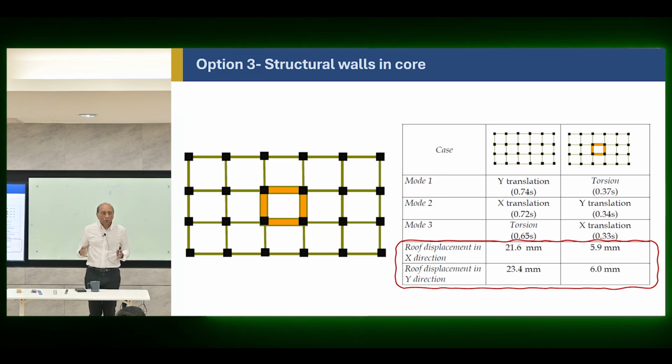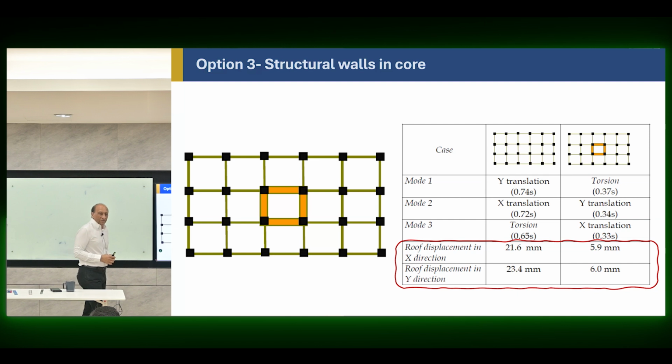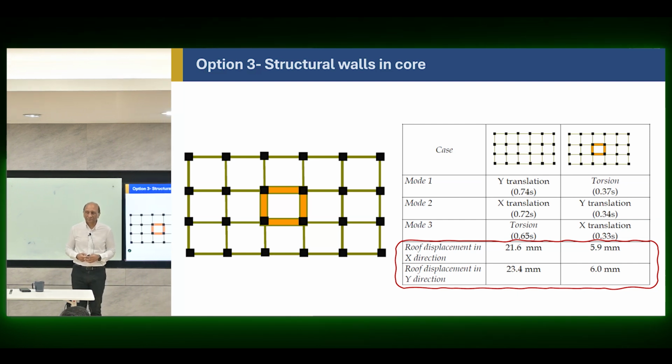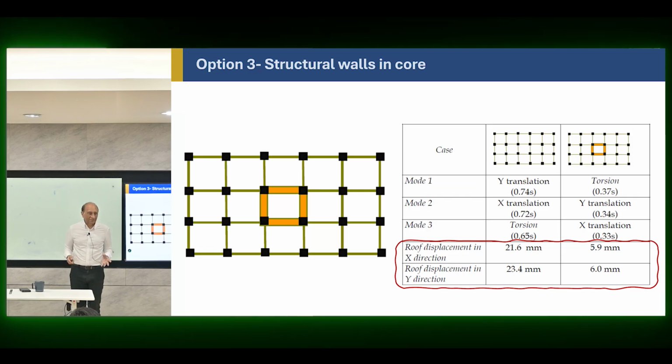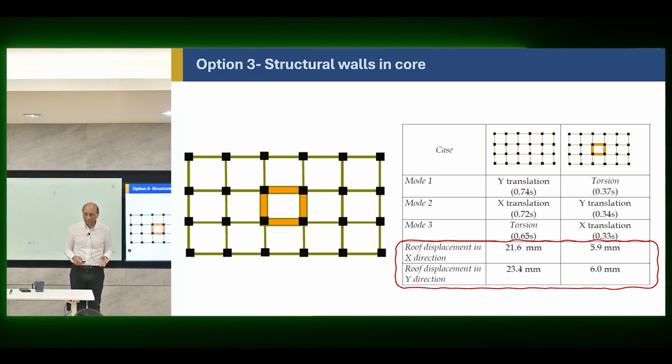And that's exactly why core-based structural systems are more efficient internally than distributed wall systems that you can do. And that's why the core, as I mentioned to you earlier, is very important for a tall building, as long as we can utilize it and we can find a place to put the core. So your core should be your first place to start if walls and frame is your solution alone.